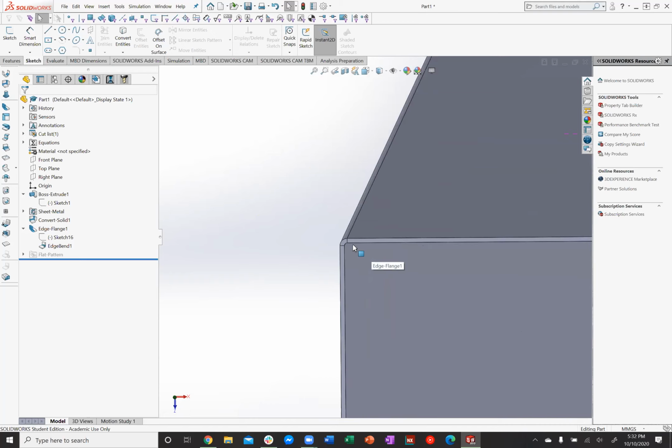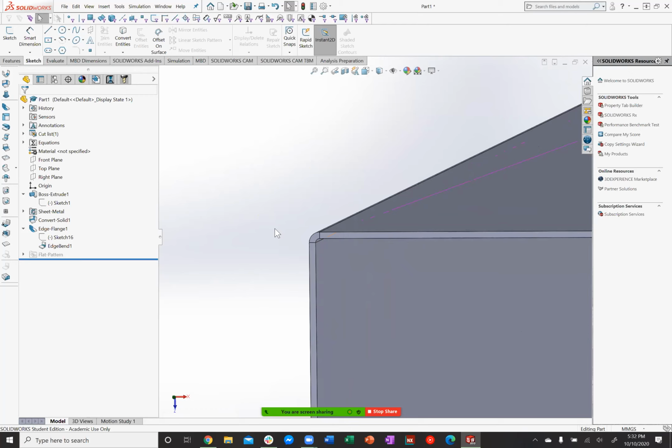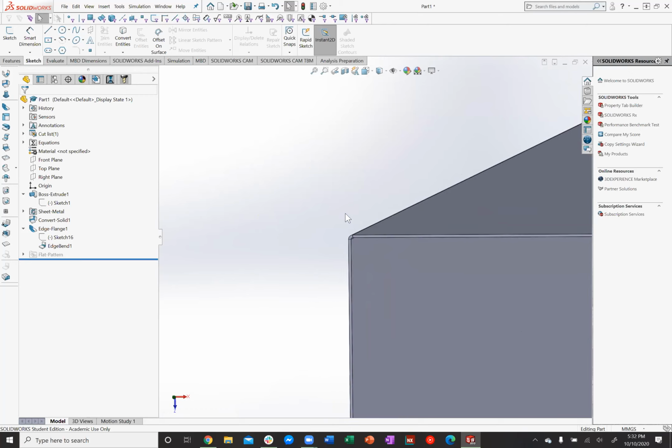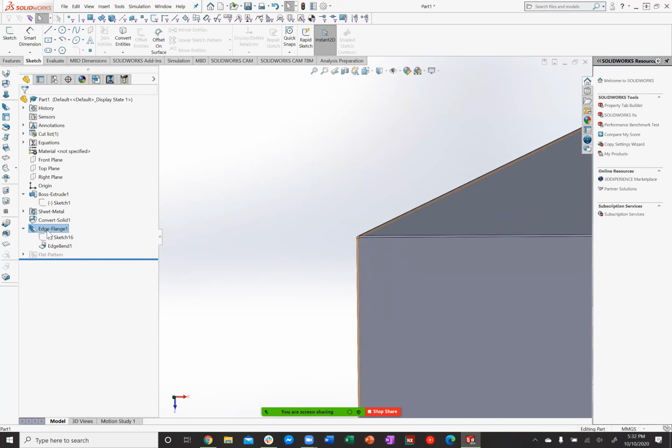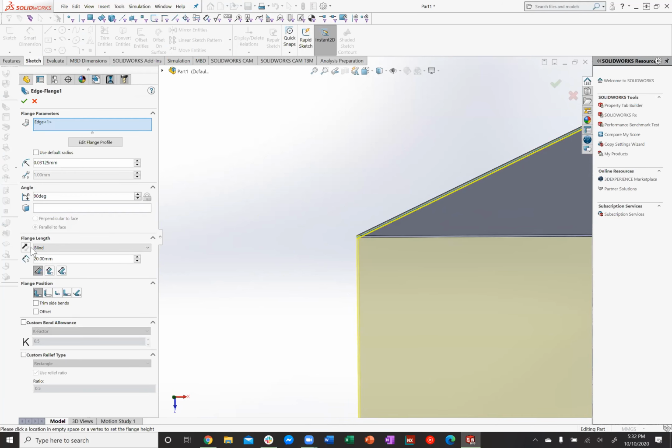And if you do a bend radius this small on a thick material, it might not work. It might even actually crack the material. But 1/32 is the smallest you could go for manufacturing. A more common one is like 1/8 or 1/16. So we'll just do 1/8 to show you.